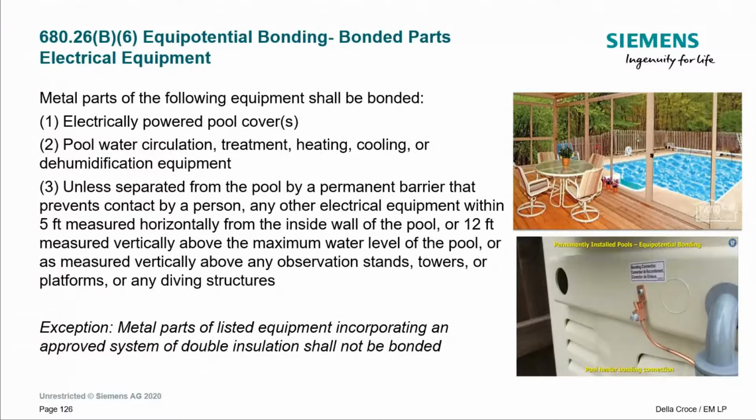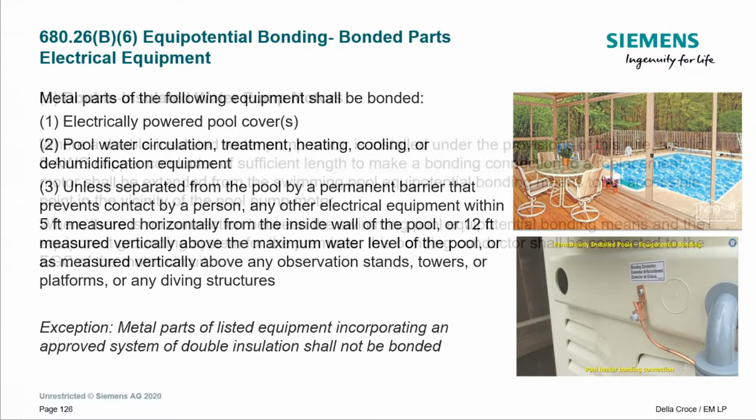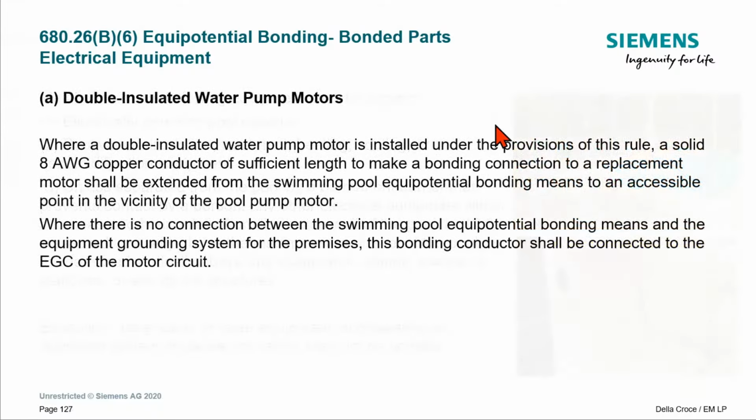So this is metal, all these frames are metal. Yep, show your cursor. We're going to say those are metal door frames. All this is metal, so it's metal within 5 feet. Cool. Yep, so it's got to be bonded. It's going to have to be an attachment to that frame. And really one attachment to one of those pieces, since they all look like they're interconnected.